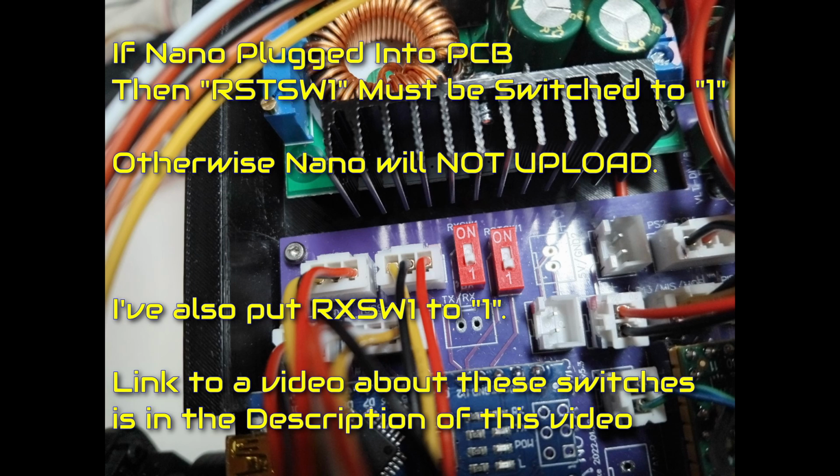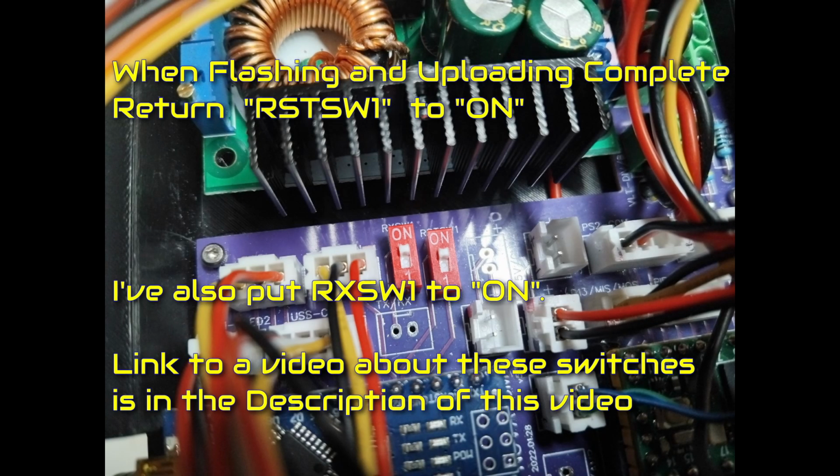That just goes to the TXRX plug, which isn't used. So the RSTSW1 switch must be in the 1 position before we can upload to the Nano. Once we've finished uploading to the Nano, we return that switch back to on. That way the code can reset the Nano if it needs to.